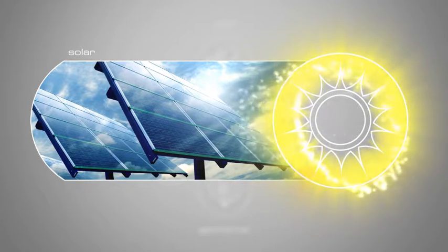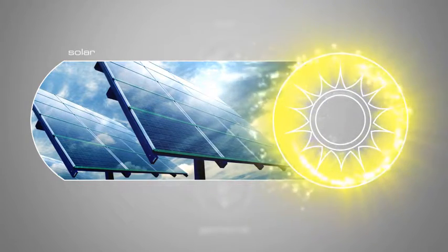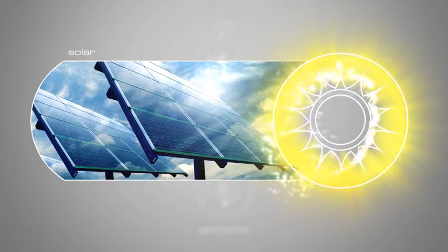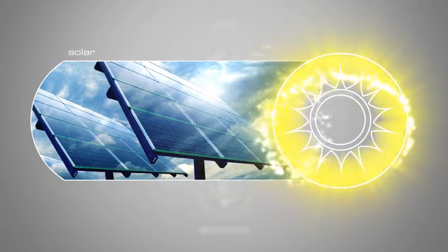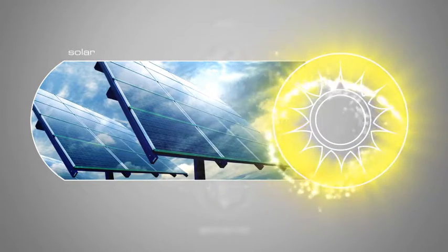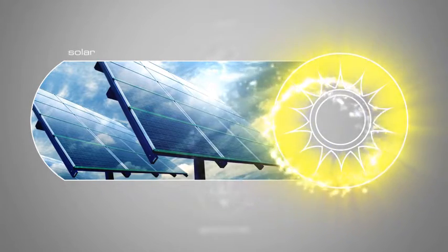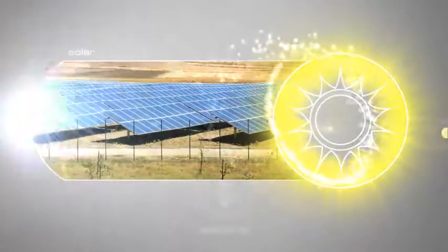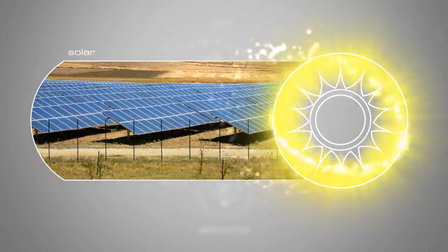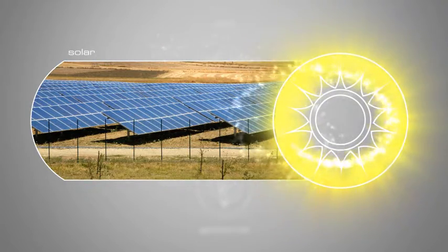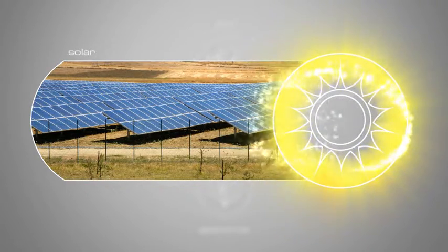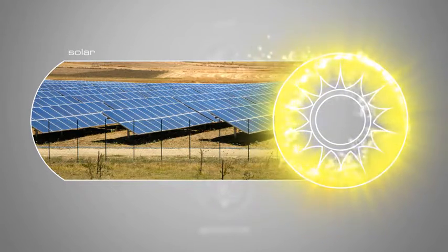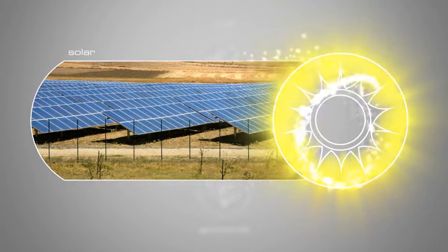Materials presently used for photovoltaics include monocrystalline silicon, polycrystalline silicon, amorphous silicon, and cadmium telluride. Since the photovoltaic materials are susceptible to damage by weather, they are packaged tightly behind an anti-glare glass sheet. When more power is required than a single cell can deliver, cells are electrically connected together to form modules or panels. Multiple modules must be connected to form arrays to provide enough power for a house.